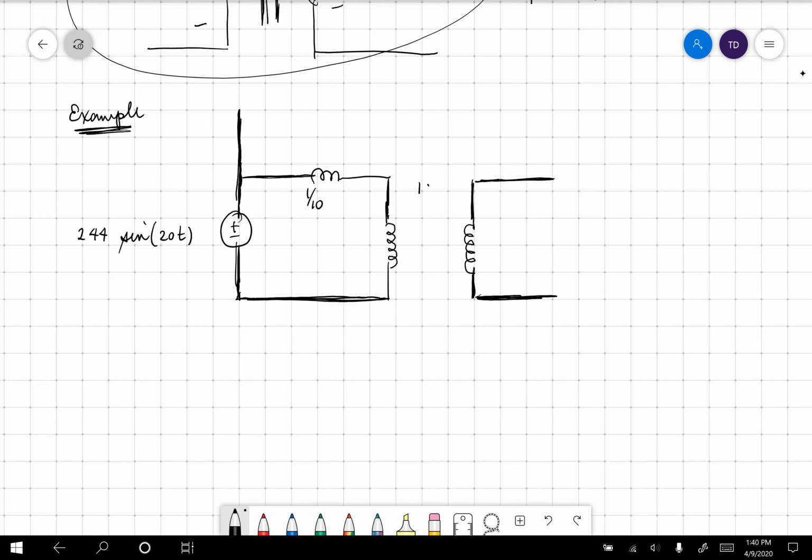All right, let's let this be 1/2. Let's put the dot notation the following way. Dot notation here and here, plus, minus. I'll put in the V2 for you. We might as well put it in now. And let's make sure we know that this is an ideal transformer. So those bars in between show the idealness of the transformer.